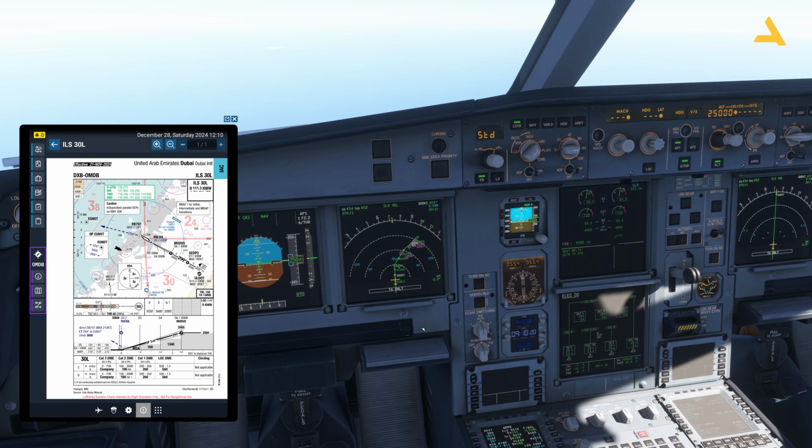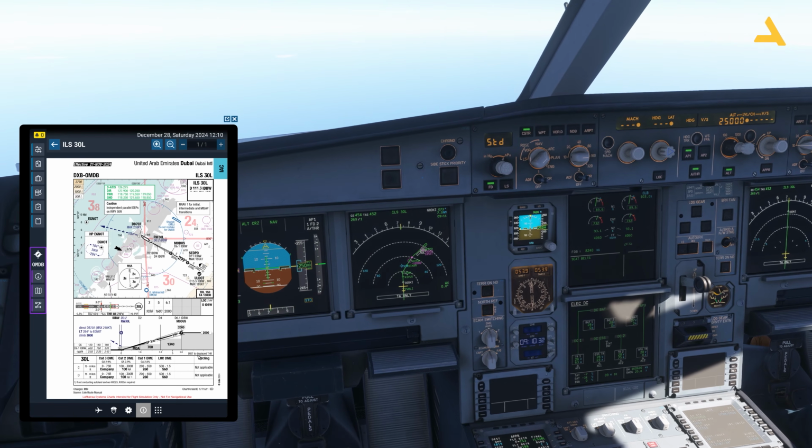So you can get the minimum altitude based on the radio readings. Radio is actually a technique in which the plane sends radio signals to the ground and it gets the altitude. And in baro, you get the altitude based on the barometric readings. So for the radio, you only use it if the ground is even. If the ground is not even, obviously you'll not get good readings. But over here for this runway, you can see for the category 3 and 2, the minimums is in radio, and for category 1 and localizer DME, it's in barometric pressure.